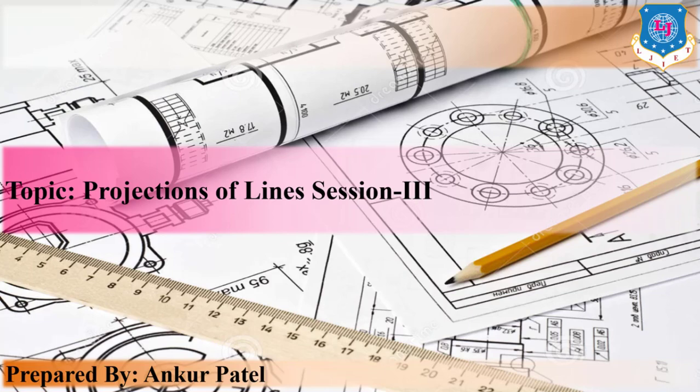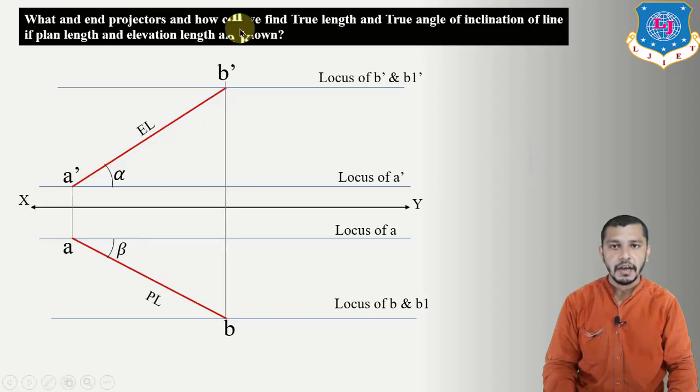And end projectors of the lines are the data related to the plan length and elevation length of the line. So before starting the practice of problems, let us discuss what are end projectors and how can we find the true length and true angle of inclination of the line if the plan length and elevation length are known.